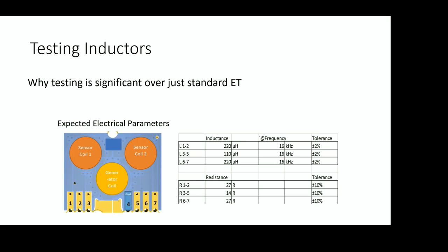So in order to make it more reliable, we strongly recommend that you do a full coil test on it. And in the coil test, you can set up your microhenry range, what kind of range you want, what frequency you want to have it done at, what kind of milliohm range you want to have for the resistance, and what kind of tolerance. So when you're doing the test, you're getting the whole portfolio here.